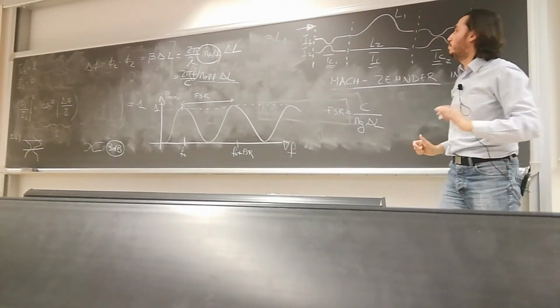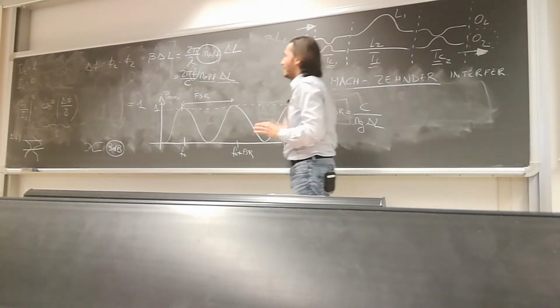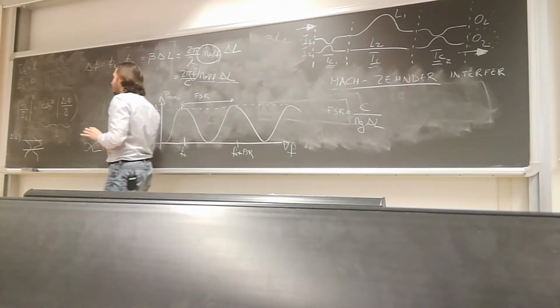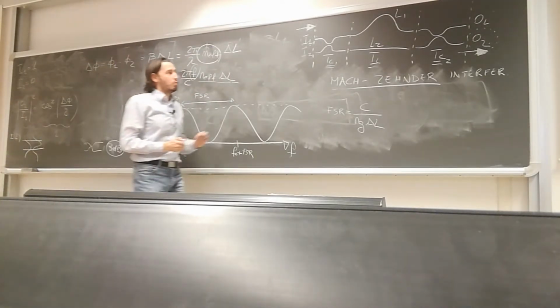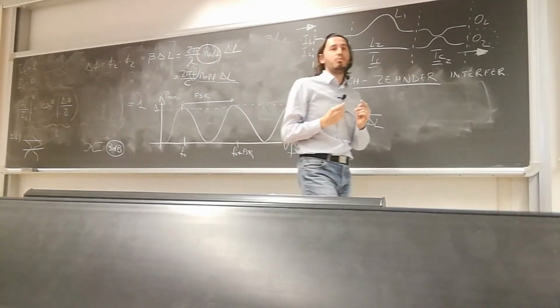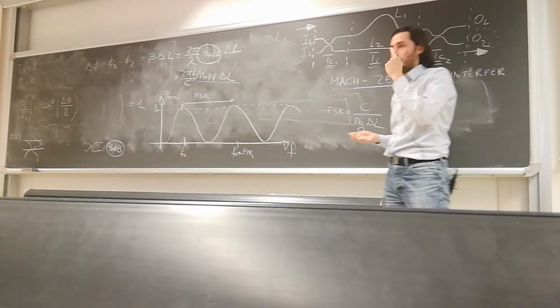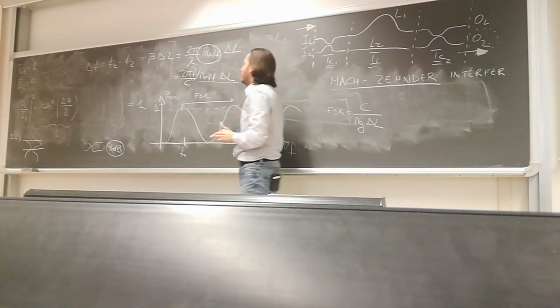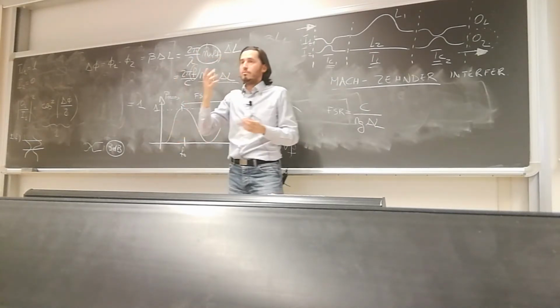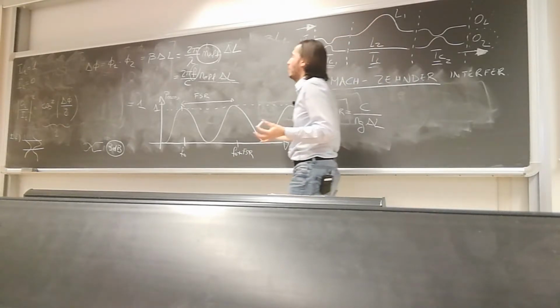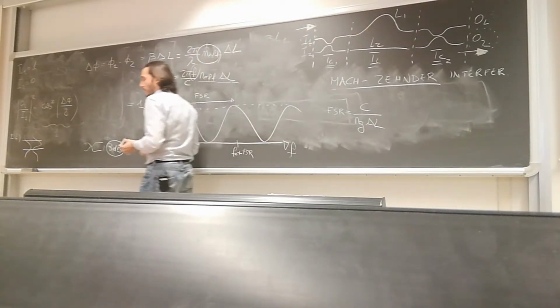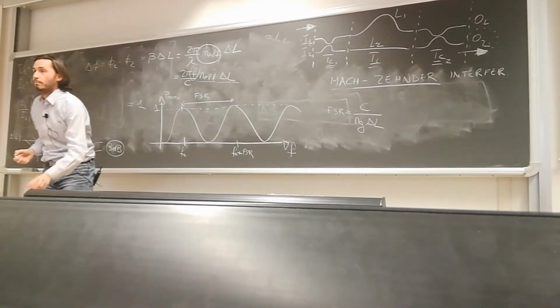So, people 99.99% of the time choose to work with single mode waveguide because in this way there is only one degree of freedom that has to be managed. That is the beta, the nef of the single mode, of only one mode. Otherwise, you have to satisfy these conditions for all the modes.